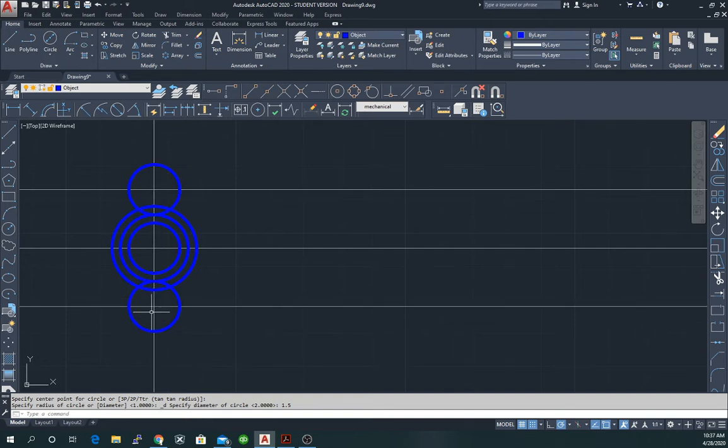Anyway, going to those holes, we see we need a 3/8 inch diameter hole and a 5/8 inch diameter hole. So a 3/8 would be 0.375. So we're going to add 2 holes. Put a diameter hole here of 0.375. And 5/8 is 0.625. So on the same location, circle, same location, 0.625.